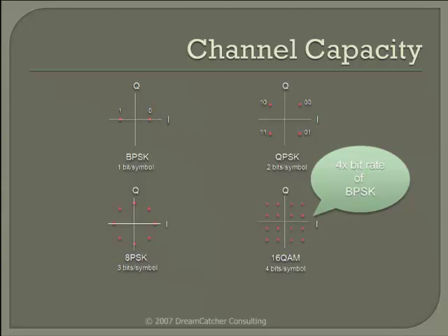This is why newer dial-up modems have higher bit rates such as 56K bits per second, as compared to many years ago, when the typical bit rate was just 2.4K or 9.6K bits per second, whereas the phone line bandwidth has remained fixed at just 4 kHz.